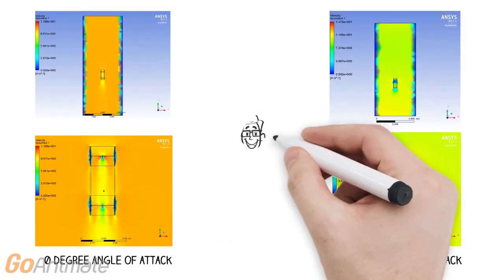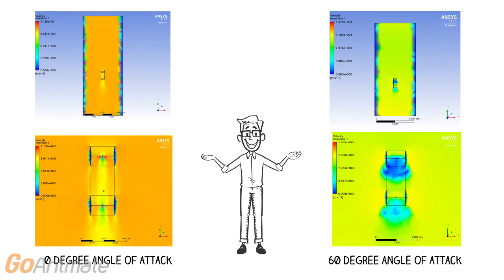These photos show the velocity of the flow over the kite on an isosurface located on the XY plane. For the 0-degree angle of attack, the greatest velocity was experienced at the braces located on the box kite. Flow decreased over the braces in the 60-degree simulation.